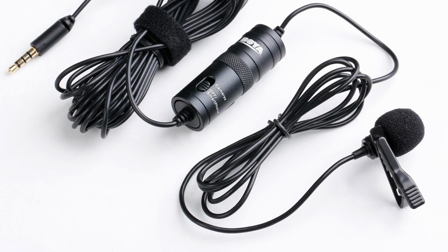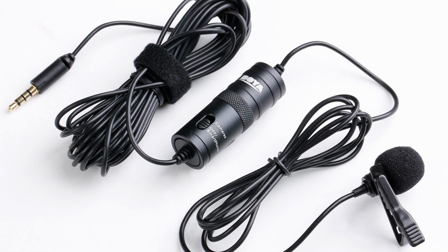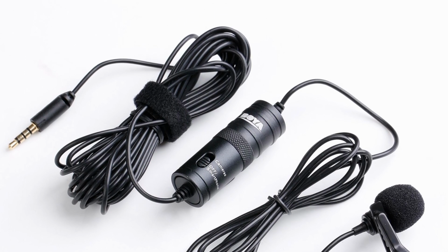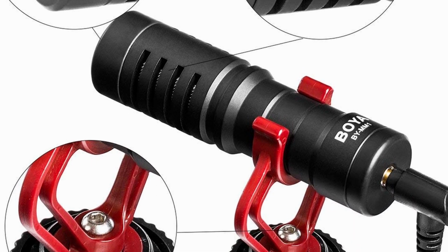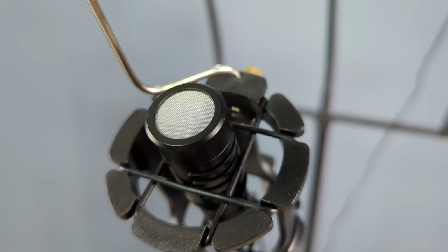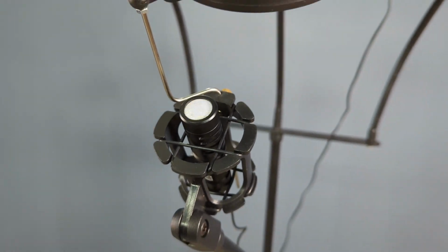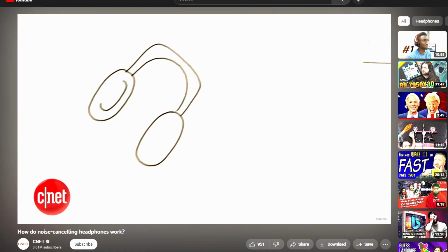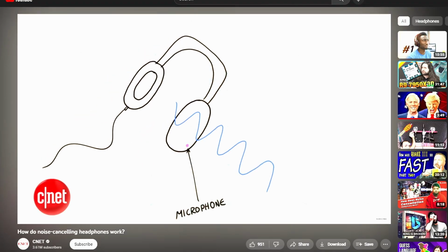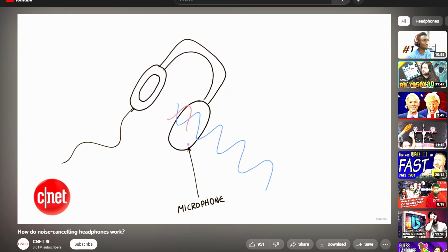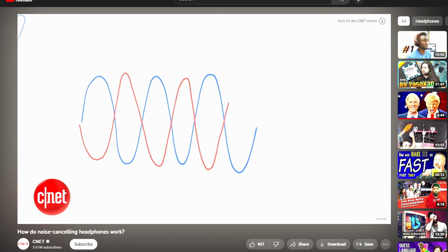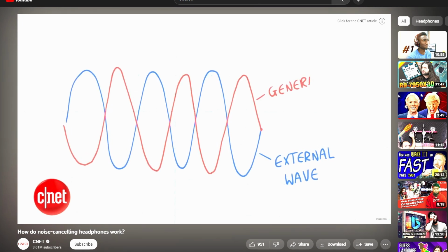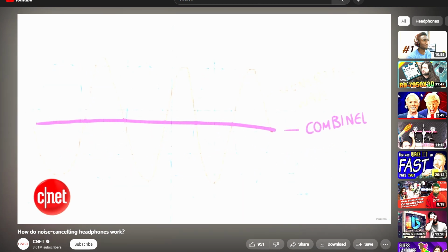There are plenty more of those names, but cardioid and omnidirectional are the most useful, popular and available ones out there. An omni mic, like this lavalier mic, picks up audio from all directions, whereas the cardioid mic, like this boom mic, picks up audio mostly from the front and its side, and almost none of it from behind it. This effect is achieved by having an array of transducers inside the microphone assembly and selectively summing their outputs constructively or destructively to boost or eliminate a specific sound.